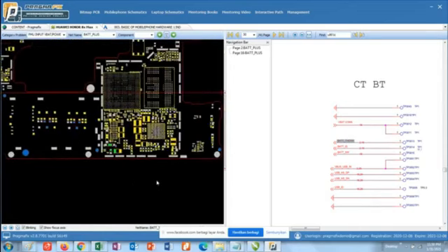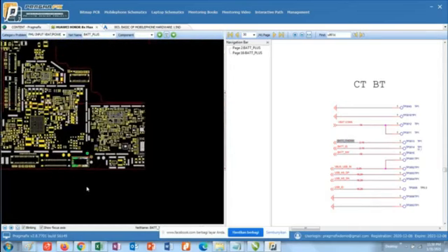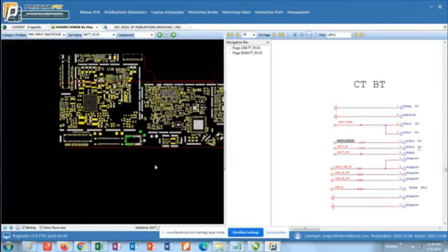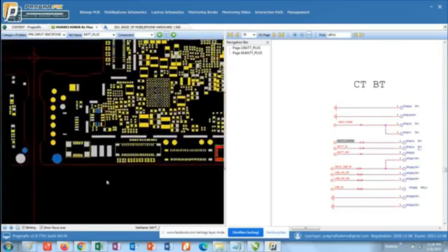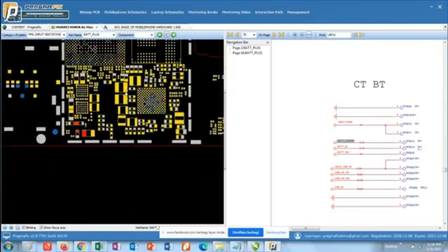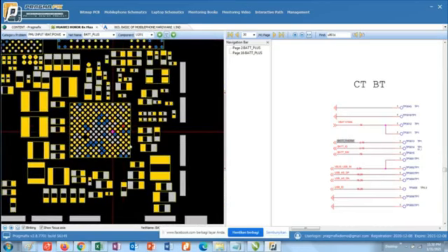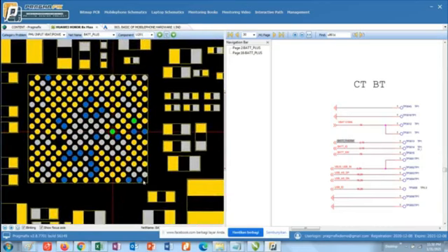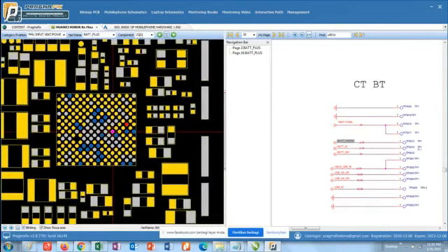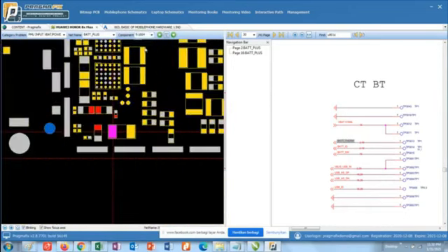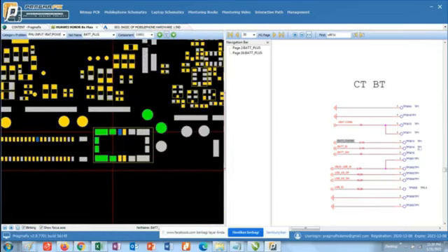On phones right now the SIM card was using 3.0, but nowadays it is 1.8. No more SIM cards use a 3.0 supply, and all SIM cards now use 1.8 as the VCC card. This battery line can go to any circuit, but on more recent mobile phones it's a series of a battery.